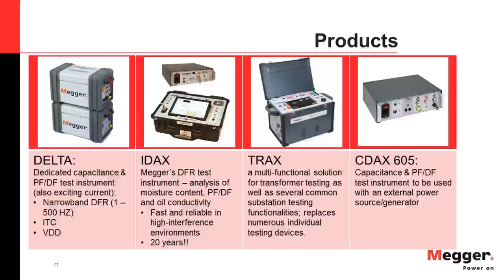For winding deformation, for sure, the much more sensitive tools for that would be doing a sweep frequency response analysis test or doing a leakage reactance test. Both of those are exceptionally sensitive. In fact, leakage reactance testing is easier to see, in my opinion, winding deformation in a transformer than it is to see winding deformation in some SFRA traces. So just wanted to add that.